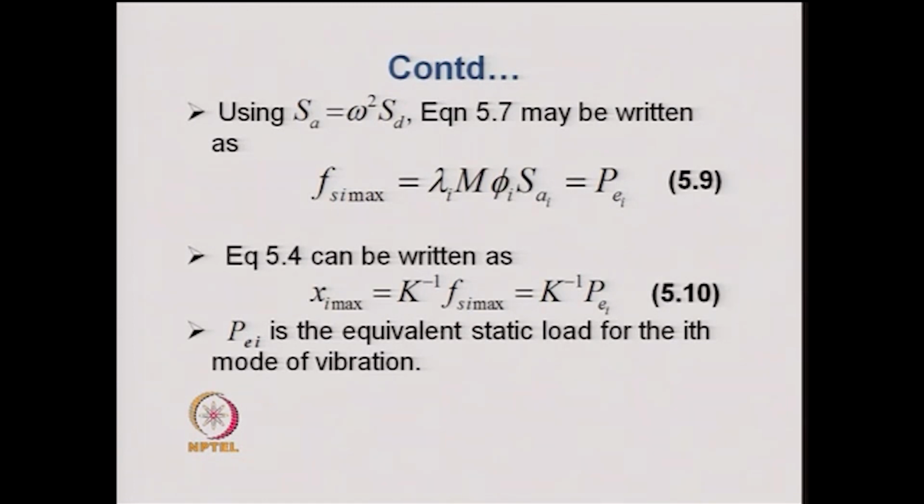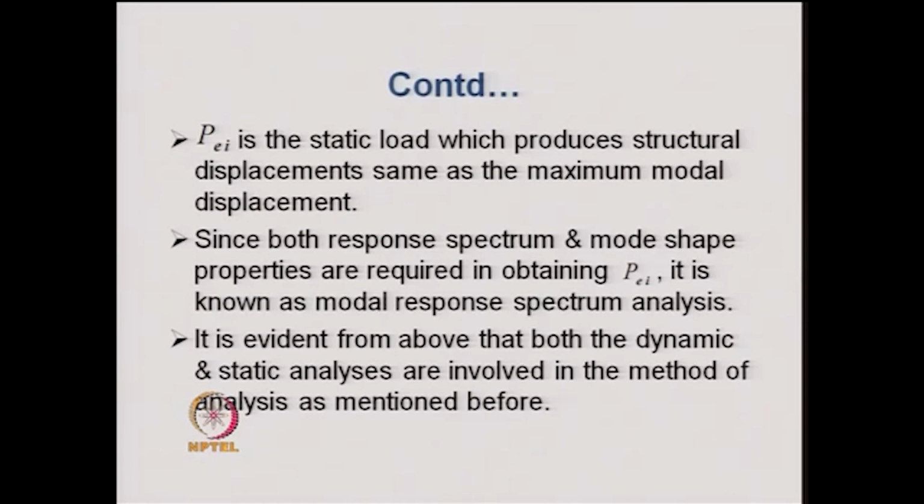And for this reason, we call PEI the equivalent static load for the ith mode of vibration. Since both response spectrum and mode shape properties are required in obtaining PEI, it is also called modal response spectrum analysis.